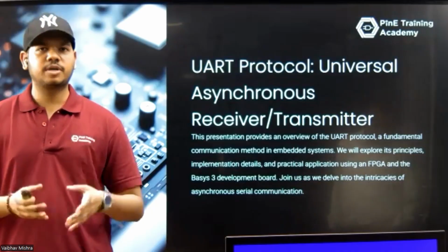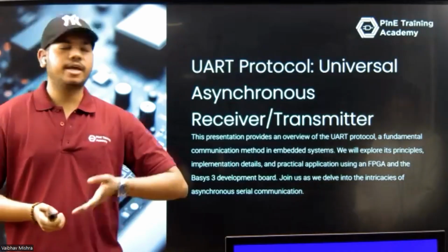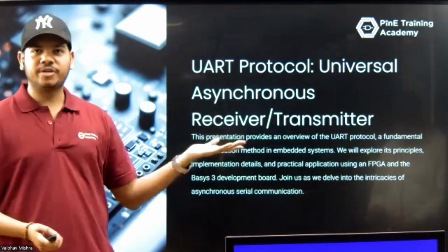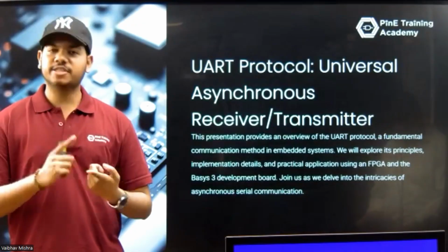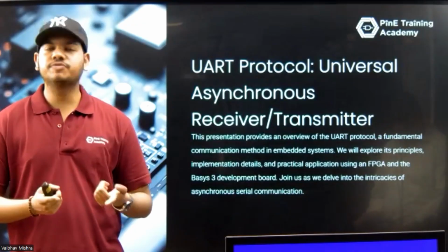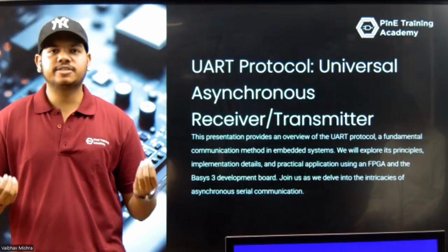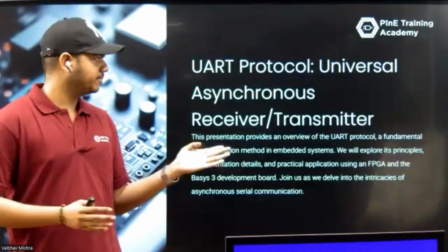Now, starting with the last part of the project, the UART protocol. UART stands for Universal Asynchronous Receiver Transmitter. When we come to asynchronous, this is the most important part of UART. Why? It is a gift because when we have asynchronous, we don't need a common clock, because making a common clock for two devices is a very tough thing. And it is also a boon and curse at the same time.